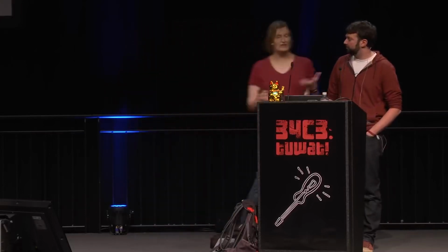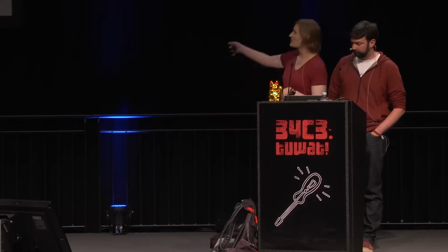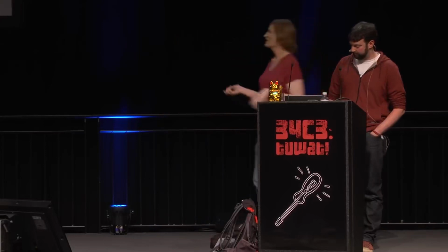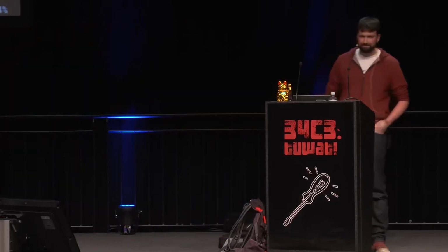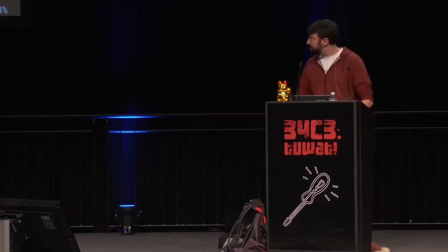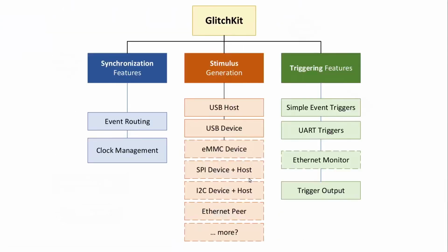But if you were to continue doing this work, one of the theories that we have is that we didn't let this go for that long. We didn't capture that much data. I don't have any secure mode chips on me, but the theory is that after this kind of thing, the SRAM you would grab would have theoretically a decrypted firmware image if it was sent a firmware image over USB. So you could kind of use this as an oracle to take encrypted firmware images and generate the decrypted ones.